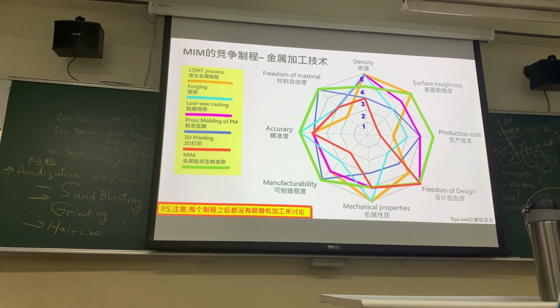Because when we do injection molding, finally we use high pressure, which we call keeping pressure. Why high pressure? Because we need to keep the shape uniform, with no shrinkage. We push the materials, then the materials cool down. The shape will duplicate the tooling cavity very well, with no shrinkage.